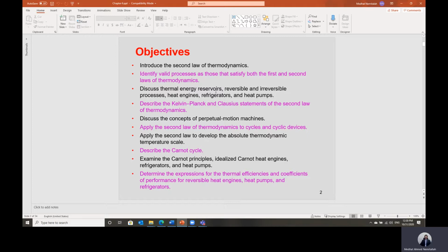In the case of a heat pump, when you want your air conditioning system to work as a heater, we just flip it to have the condenser inside, which rejects the heat to the inside. And we have the evaporator outside, so it will absorb heat from outside and reject it inside.